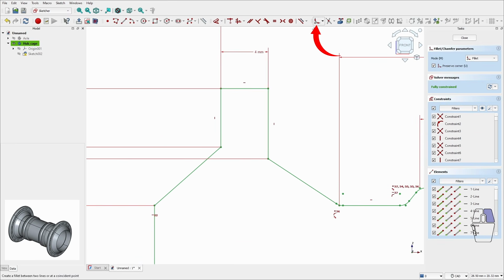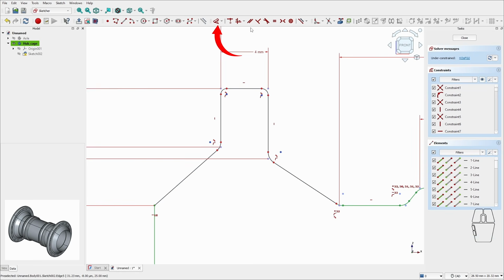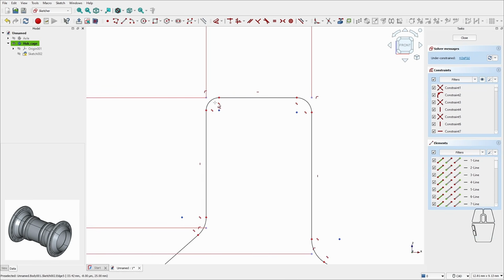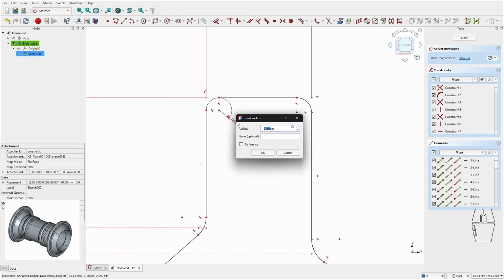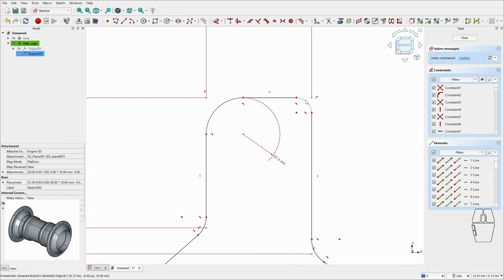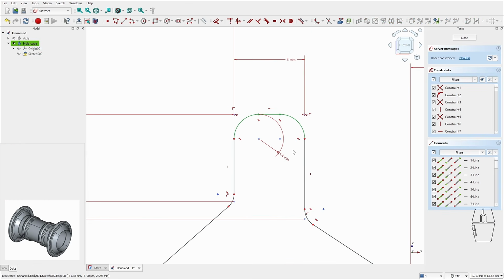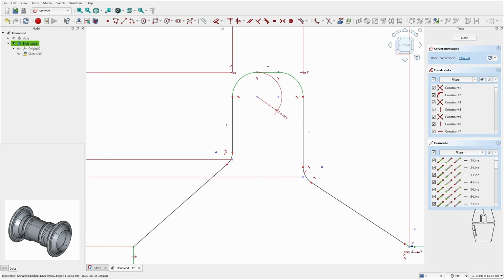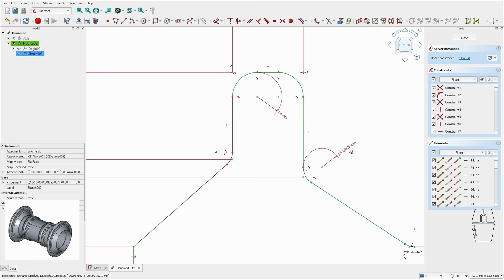So go ahead and click on the fillet icon in the top menu. Then, select the 4 points in the spoke mounting area by left-clicking on them. Right-click or press Escape to stop using the tool. Then grab the dimension tool and set a radius of 1.4 millimeters for the 2 upper fillets and 2 millimeters for the 2 lower ones. You can either set a dimension for one fillet and then apply an equal constraint to the other, or just use the dimension tool to define all the radii. Totally up to you.